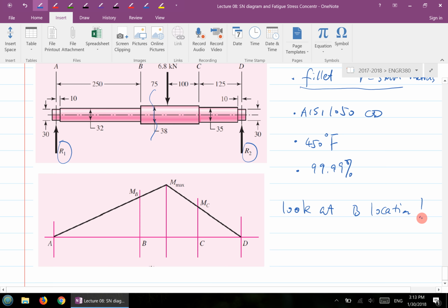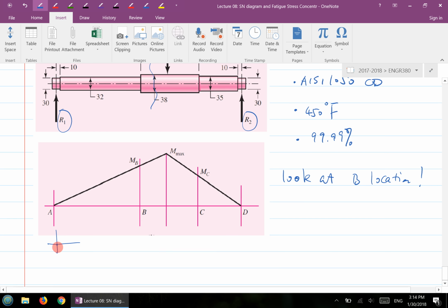So you're only considering bending moment, with the bending normal stress caused by the bending moment. If I look at the free body diagram, this is the bending moment diagram. There's also a shear force diagram, right? If you cut a cross section, shear force will cause what type of stress? Shear stress. We call that the bending shear stress in this case.